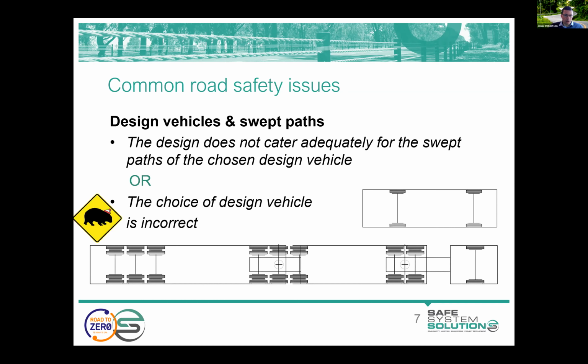You can get out on site and observe the vehicles getting about at your project location to determine what you think is an appropriate design vehicle. Keep your eyes peeled for land use in the vicinity of the project and potential land use changes, and the effect that might have on the vehicles that are being attracted to that location.